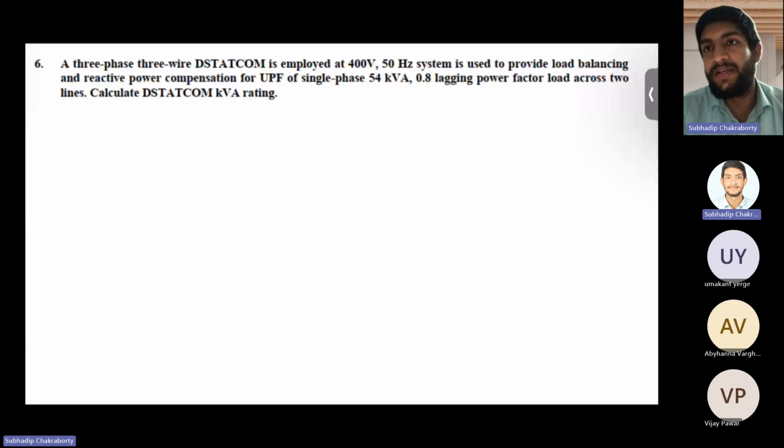And whatever you calculate using the RMS value is also an RMS quantity for AC calculations. So you don't need to divide in that case by anything. It will come as the RMS value only. If you want the peak value, then you have to multiply by √2 for sinusoidal signals. If nothing is mentioned in the question, then it is implying to calculate the RMS value.